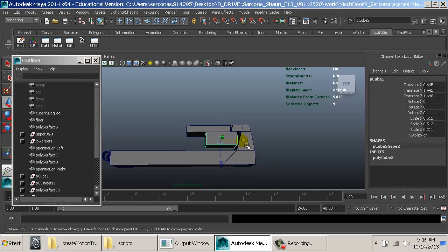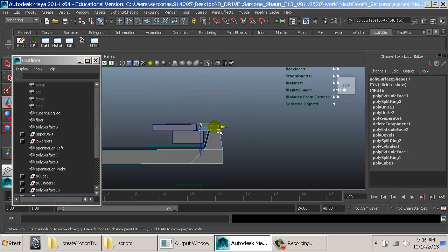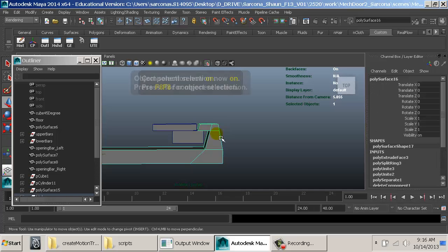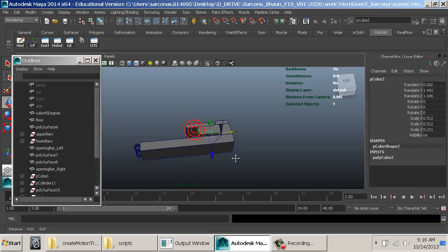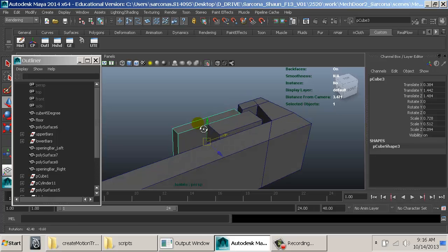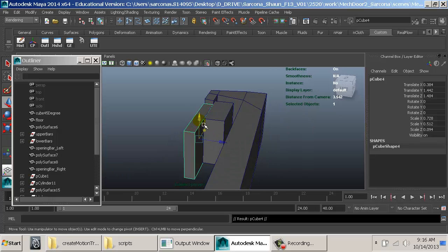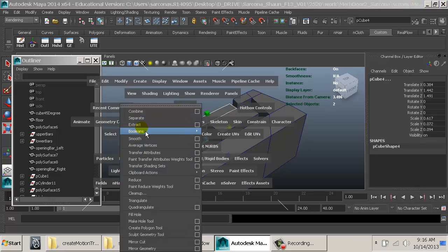Okay, and then when this door unlocks, this is going to go, and then this thing can open up. Let me scoot this over a little bit more, just like how close the cube was to the rest of that. Okay, so that looks kind of neat. Just to sell the idea of this thing working, I'm going to duplicate this, scale it down like that, and then just do a mesh booleans difference.